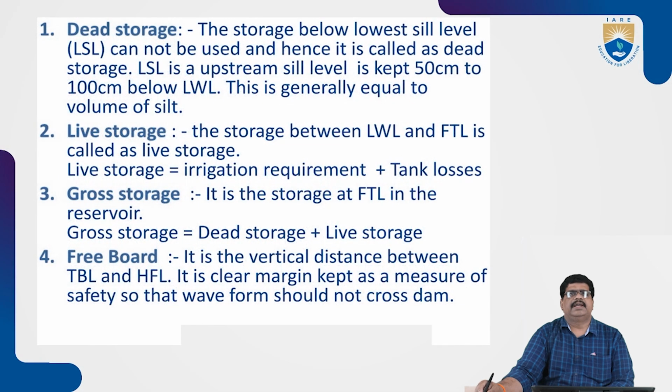So next, dead storage, live storage, gross storage, and the freeboard. What is meant by dead storage? These points are very important components for the estimation of the reservoir. So next, dead storage. What is meant by dead storage? The storage below the lowest sluice cannot be used, hence it is called dead storage.